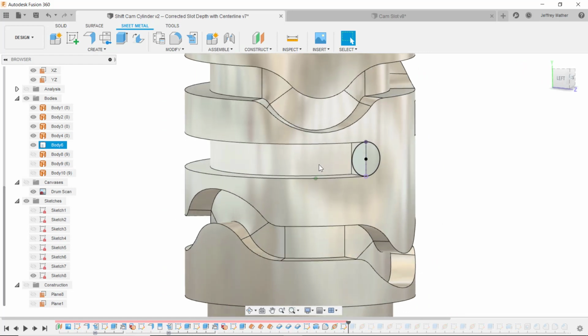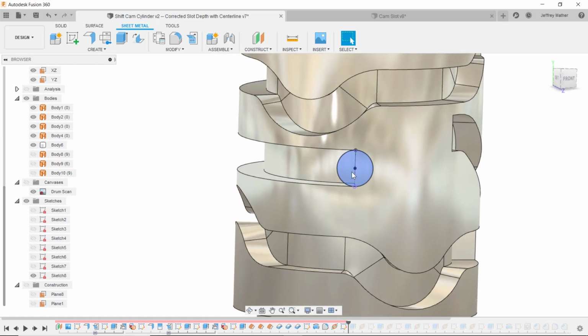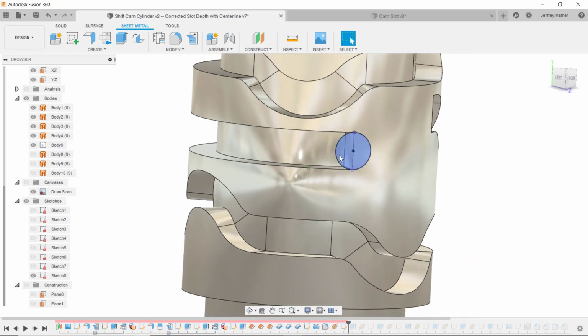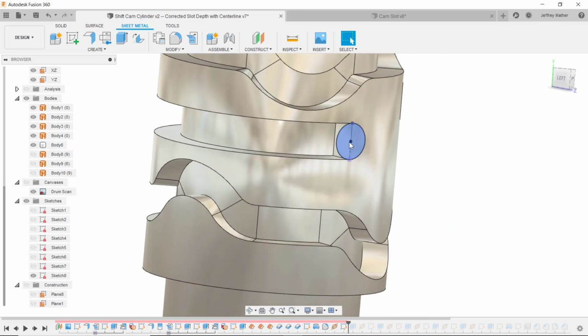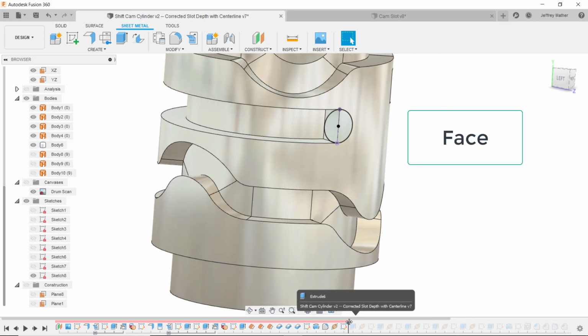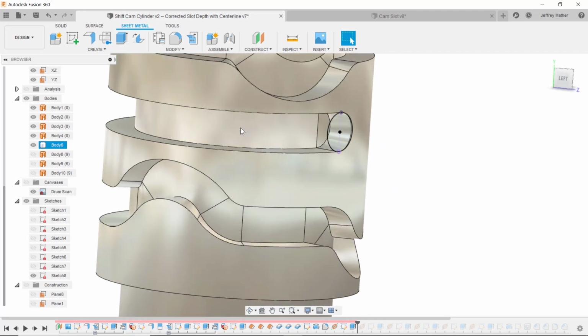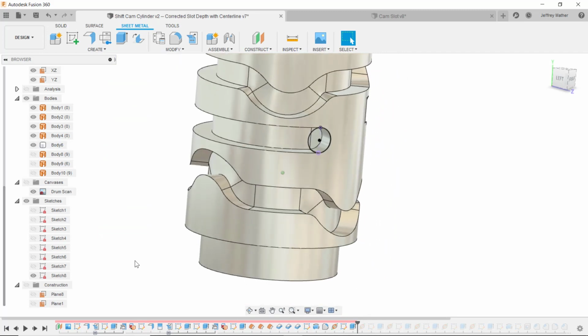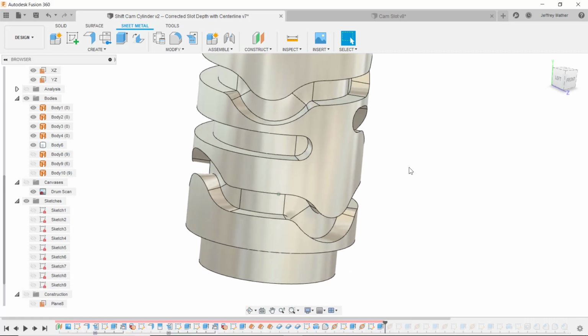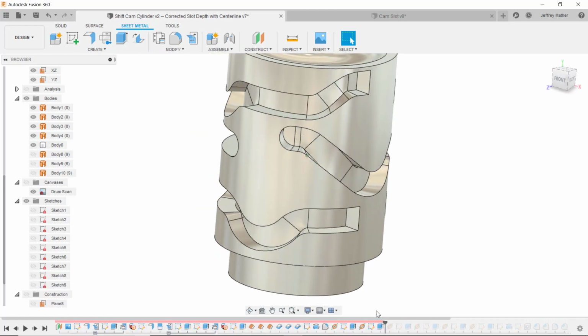The cylinder is rotating as it is being cut. When it gets to that last spot, it actually leaves a little bit of a flat there. Half of this will end up being a planar surface. So I do an extrude cut so that there's a planar face right there because the rotation stopped. And the same way at each end of this. So I did the same thing at each end of this slot.